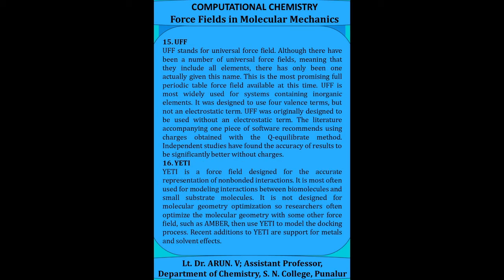Next is UFF. UFF stands for Universal Force Field. Although there have been a number of universal force fields, meaning that they include all the elements, there has only been one accurately given at a time. This is the most promising full periodic table force field available at this time. UFF is most widely used for systems containing inorganic elements.